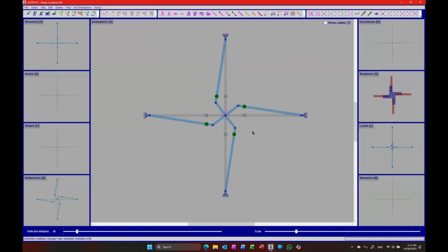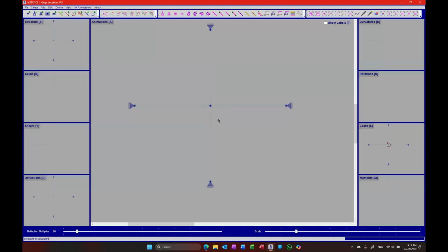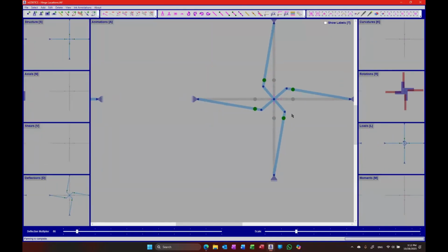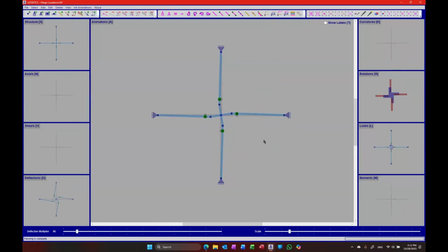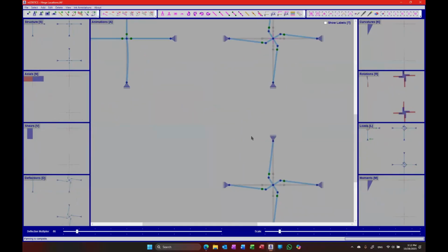But we also have to make sure that we don't have everything connecting to the element as a hinge, because then we have a mechanism at that joint specifically. In this case, you can't see it because the joint has no dimensions. But when I add the dimensions, you can see that only when you have at least one element connecting to the joint without a hinge, you can have a structure without a mechanism, basically. So we have to keep that in mind.